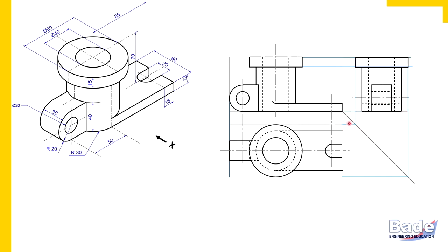Can you see that dotted rectangle? Remember, each and every part, each and every surface, each and every edge you must be able to identify in orthographic views. Now this horizontal plate, its largest surface is in the top view. In the front view it is a rectangular strip, and in the side view also it is a rectangular strip. Watch here. This horizontal dotted line, 60 millimeters from left to right. This is just the top surface of the plate.